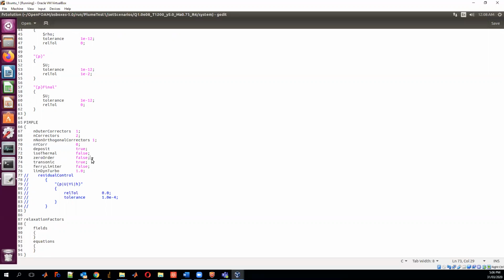If we set this to true, then we only have decoupling of settling, but acceleration is not decoupled from the gas flow. If we set this equal to true and we set the particle size as equal to 0 in the previous file, that'd be like a dusty gas approximation. Transonic, if you want to be able to track shocks, this also needs to be true, so that slightly changes the numerical method.